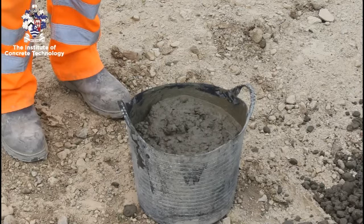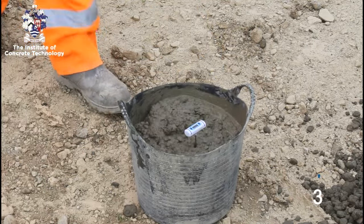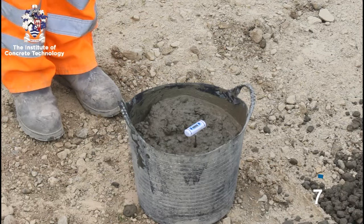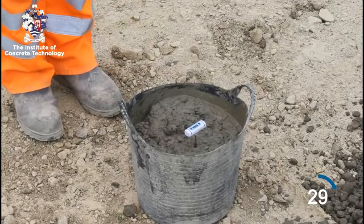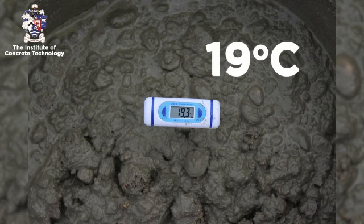If the temperature of the concrete is required, it must be measured by the insertion of the thermometer to a depth of approximately 50 mm, and the reading of the temperature must be taken between 30 seconds and 60 seconds after insertion. The temperature must be recorded to the nearest 1 degree Celsius.